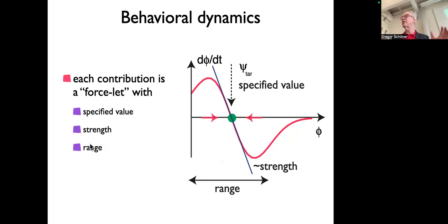So I already hinted that the target is often formulated as a sinus function. That would mean its strength has no limit. It just has one fixed point where it goes to zero behind you, and that's because you're assuming that you always want to move to the target irrespective of where you're currently heading. So you're not losing that constraint just because you're not heading right. While the obstacle will typically limit the range. For instance, if you're moving in this direction and the obstacle is far enough on the side, then you don't want to be influenced by it anymore, right? It's not relevant to you anymore.